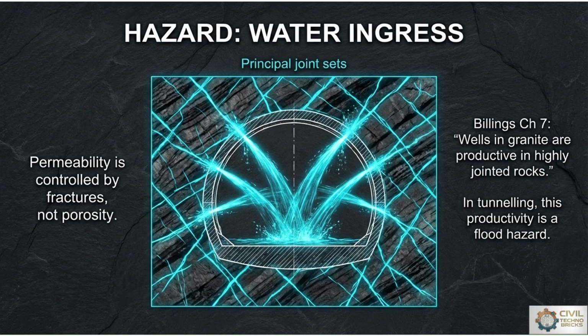So when we are following the construction activity of tunneling, we have to provide casing to the whole tunnel, otherwise there may be n number of cracks through that rock surface, and it may create a water ingress hazard. So the tunnel protects from hazards such as roof collapse, rock burst, water ingress, and gas emissions. So we have to provide the safety or the casing to the whole tunnel.